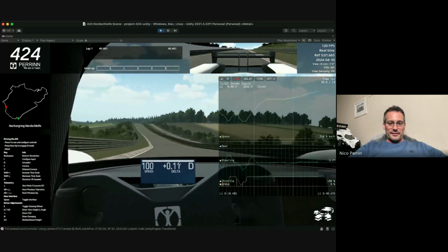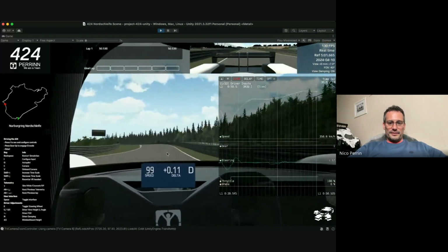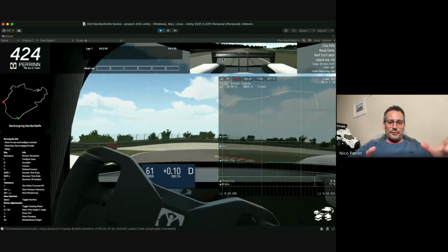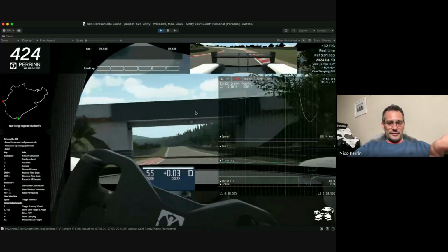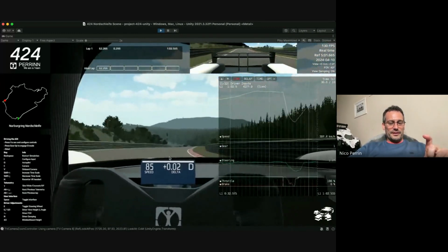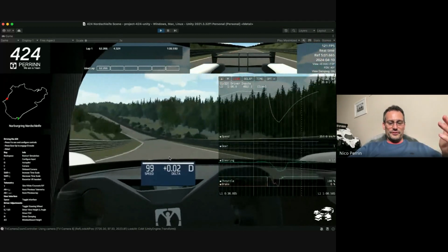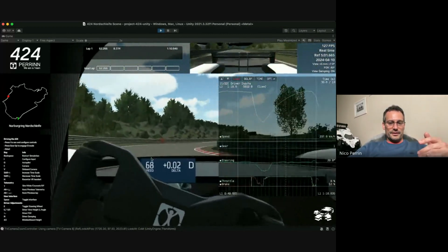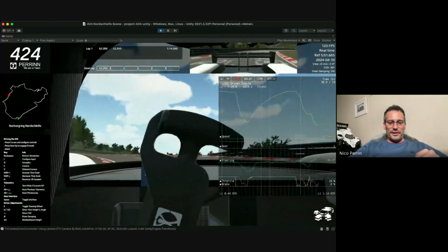This bar here tells you when the DRS is active. You see the rear wing at the back. DRS has just gone off. Automatically, we have a section where the DRS is closed just to give stability in that high-speed corner. And now we exit again. DRS comes on automatically on this car. After half a second on full throttle, DRS opens. As soon as you touch the brake or you release throttle, DRS closes. So the bar goes on and off quite a lot around the lap.